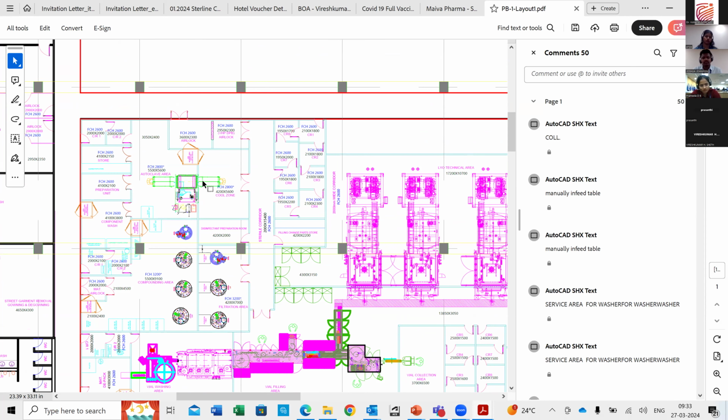When you unload it here, there'll be a laminar airflow unit which will be kept here. There'll be a ceiling suspended laminar flow unit in which you will unload the component. This room is also a grade B, but there is the laminar flow area. The area under the laminar flow can be claimed as a grade A area itself.